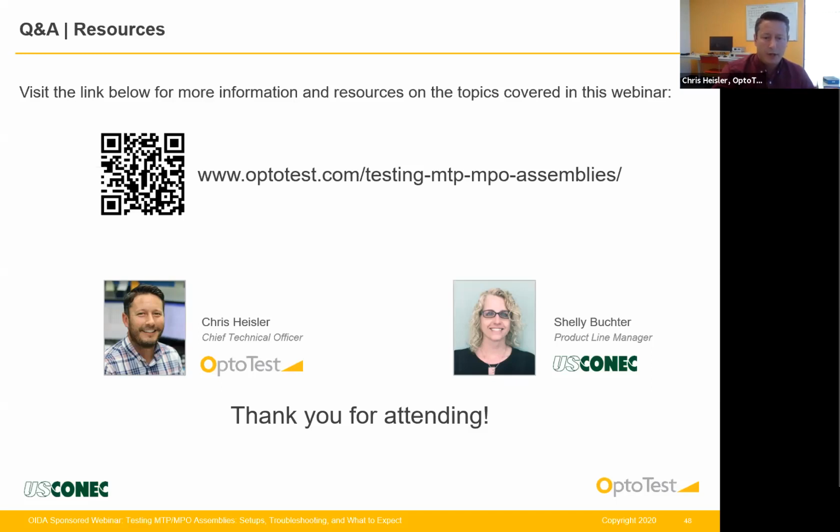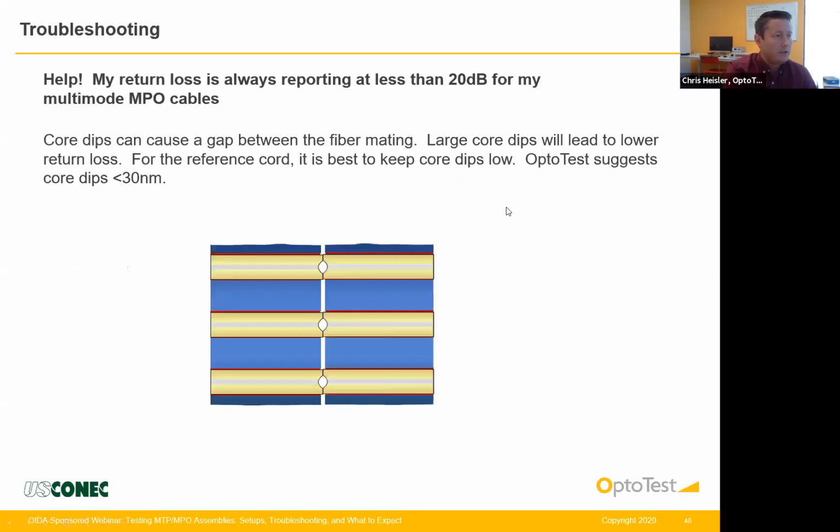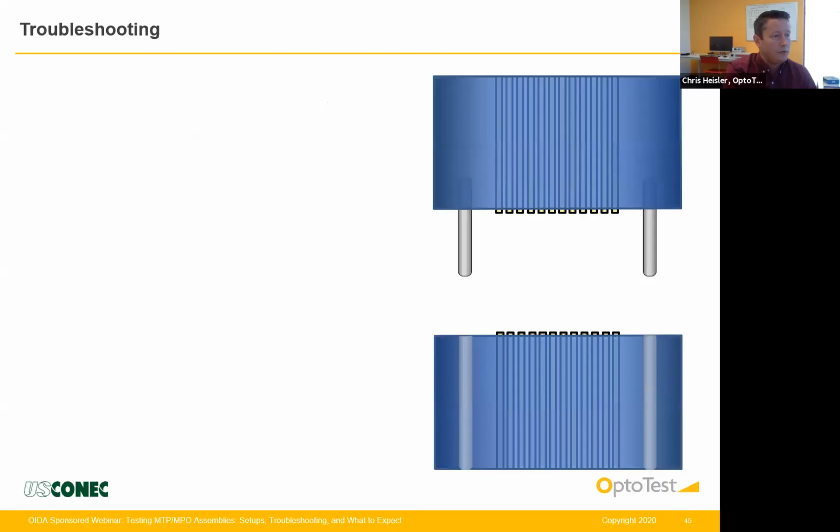So the unidirectional method is measuring insertion loss across the entire assembly. So it's going to get ILA and ILB, and those will be a combined measurement. Now, RLA is measured on the front side of the DUT, and RLB is measured on the back side of the DUT. So RLB actually has a little bit of influence due to the insertion loss on the front side of the DUT.